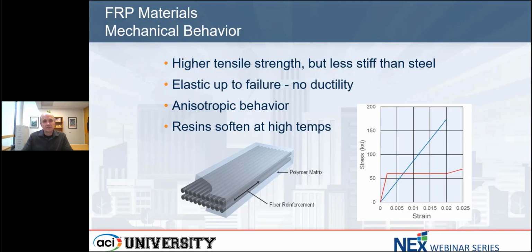But beyond strength, the other properties of the material also vary depending on the direction you're looking at. So strength varies depending on the direction, but so does modulus of elasticity. So do things like thermal conductivity and electrical conductivity. And so do things like coefficient of thermal expansion. I mention these because they are important when we start thinking about using this as reinforcement for concrete.